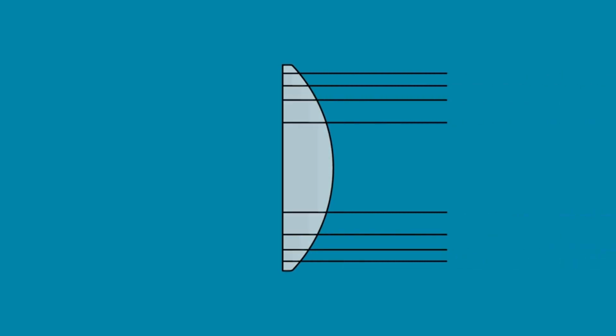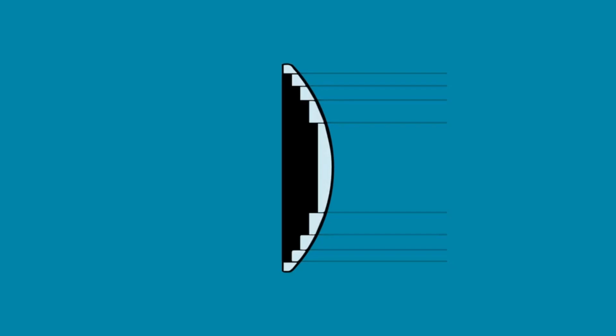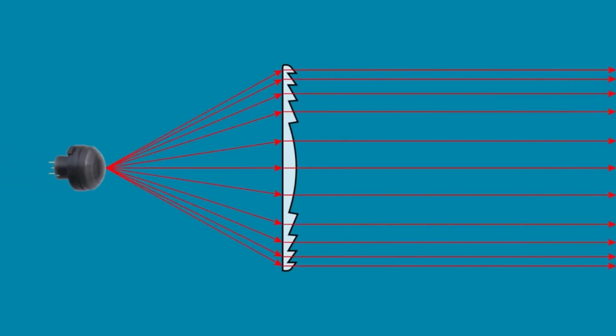With a Fresnel lens, the curvature is broken down into slices, and those pieces are flattened into a much thinner lens, but still maintains the angles of the original. By adding a Fresnel lens, the detection range of a PIR can be increased significantly without drastically affecting the size of the device. Fresnel lenses were traditionally made of glass that can withstand the heat of the lamps. Since PIR sensors don't get hot, their lenses can be made of plastic.